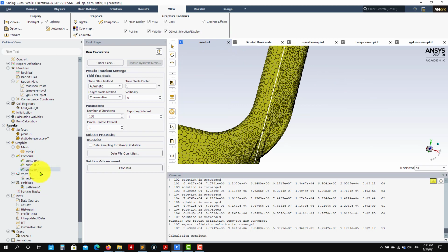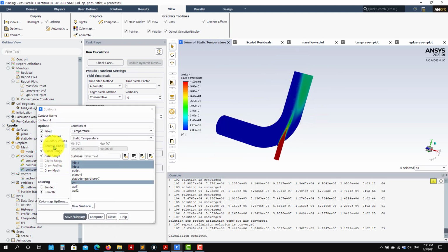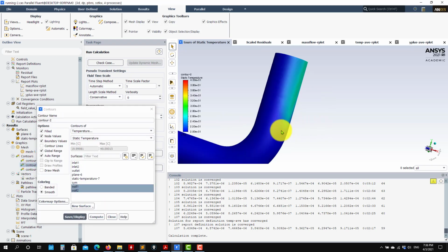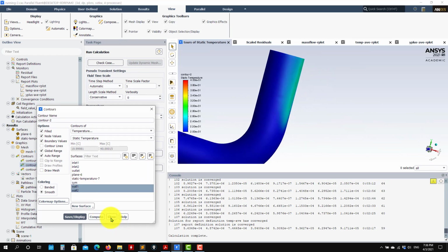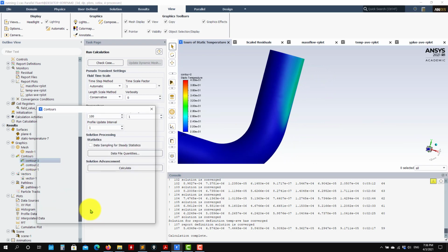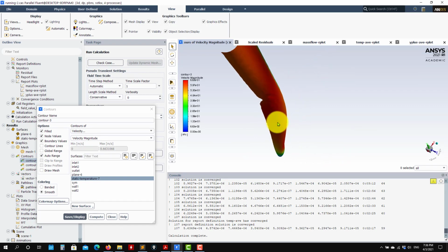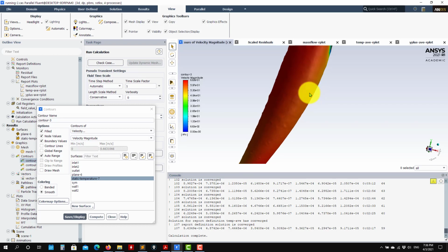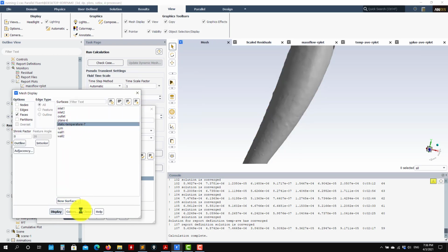So now we can also do the post-processing. Pretty much the same, nothing should change. Probably we get better results now, with the finer mesh. That is the hope. A finer mesh will give you better results. And let me go here. Probably if you compare the previous one and this one, you will see that the isosurfaces are also better resolved. So I can draw the mesh there just to see.